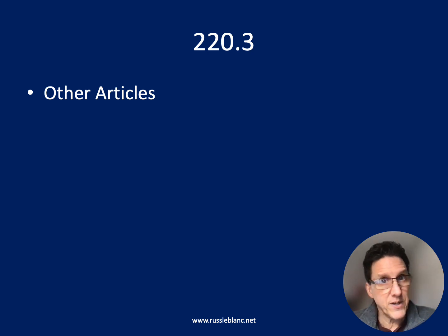So we don't really need to specify that in 220.3. That's just how the code works. But for rules that aren't in chapters 5, 6, and 7, well, then we probably need a heads up that, hey, you know what? Not all the calculation rules are in Article 220, right? So take a look at Table 220.3 if you're dealing with any of those specific calculations, okay?